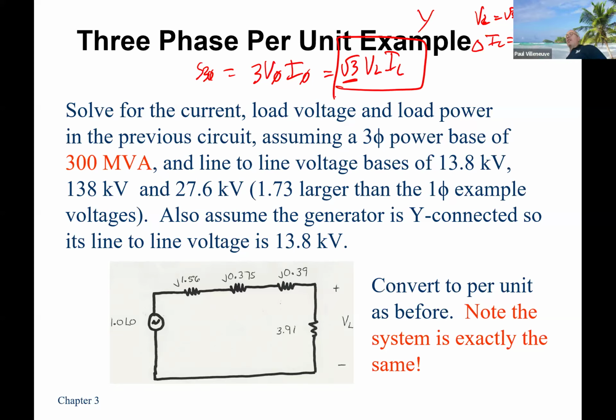Am I dealing with phase quantities or line quantities? The second one, square root of 3, V line, I line, it always works out in the wash because if the voltage is off by the square root of 3, the current will balance things out for you. So that's why we can use it without having to worry about it.